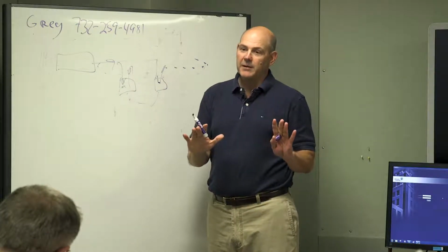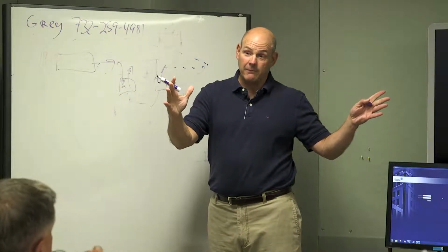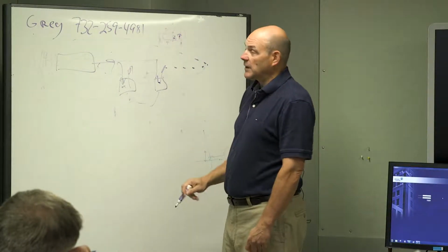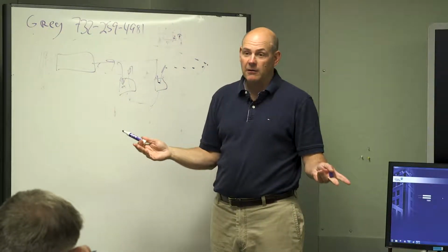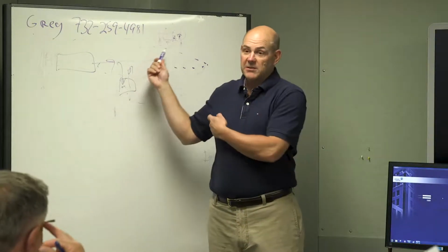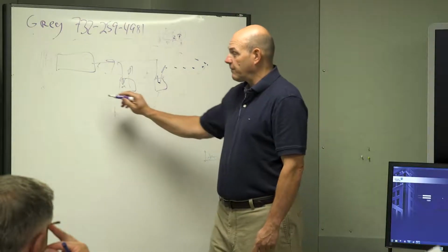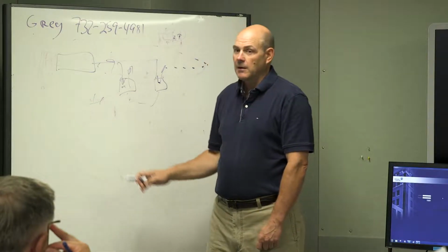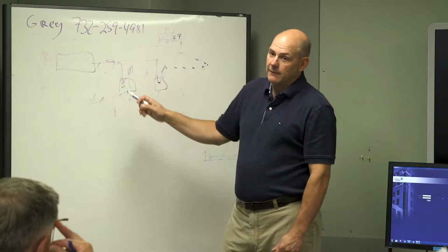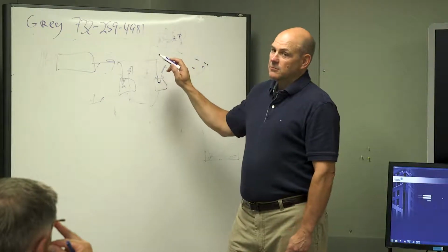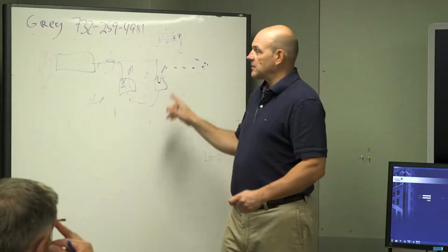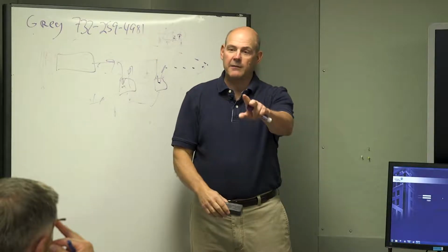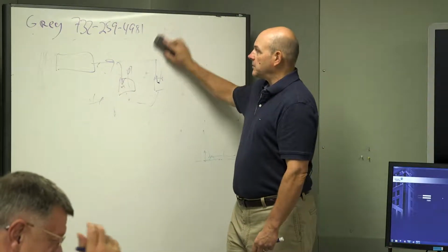So we try to limit the communication outside of the panel. The only thing we share is outside air temperature. That's one that every single thing needs because the air handler is going to control based on outside air temperature. If it's 45 degrees out, we want more outside air. If it's 80 degrees out, we want less outside air. So we want to share that, but we want to minimize what we share because that slows the whole network down. So we keep adding the IOMs so we don't have to go outside for information.